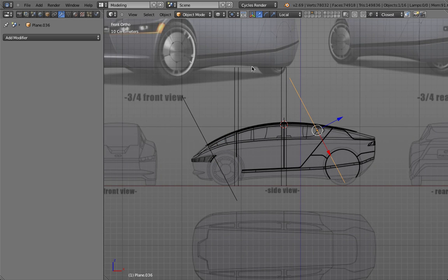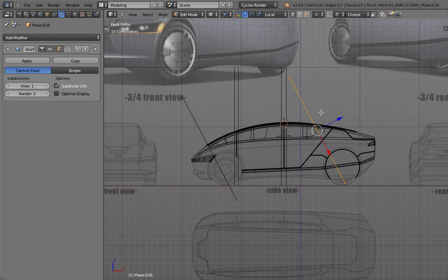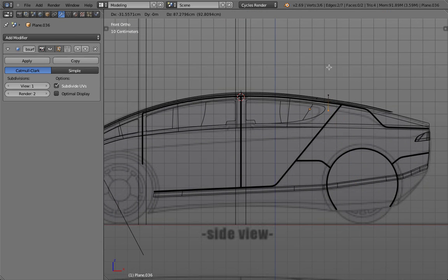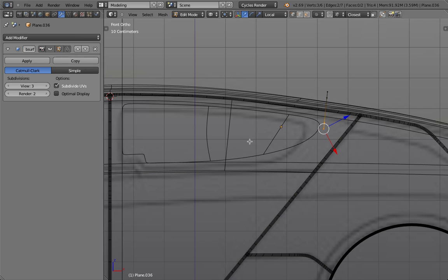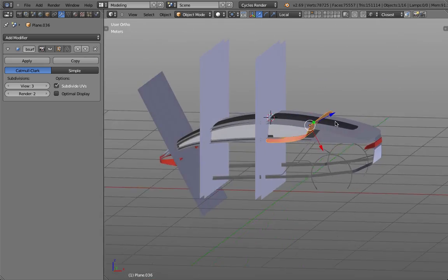Okay. The back is a little bit tricky because this is rounded, but that is not really a problem. So what we do, instead of having just a flat surface, we simply will create a surface that is rounded or arced. So for example, this part I move down to here. And then I have to see maybe how I have to lay out my geometry with the least amount of points possible, so you have nice and even curves. The more points, the easier you can make the curves crooked or uneven. So, okay. Let's shade this one smooth.